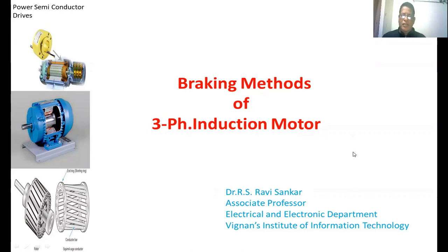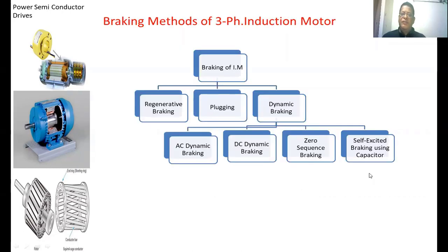Welcome back to the class on power semiconductor drives. In this lecture, we are going to discuss the different braking methods of a three-phase induction motor. Braking means intentionally decreasing the speed of an induction motor. The braking methods of a three-phase induction motor are basically of three types: regenerative braking, plugging, and dynamic braking.